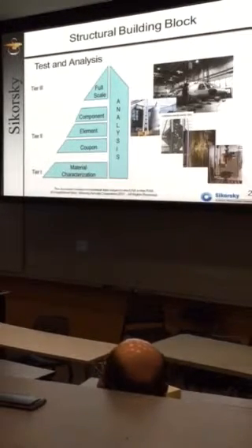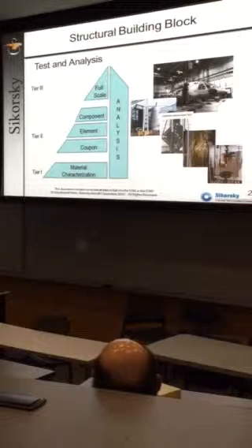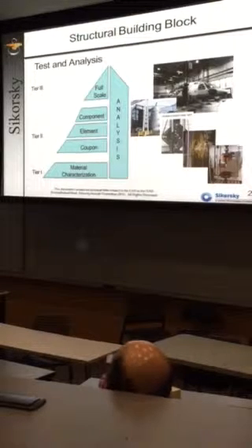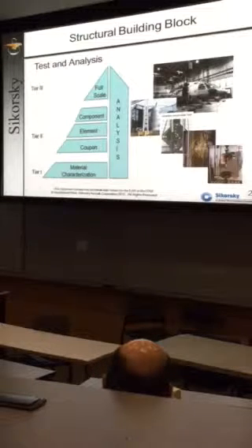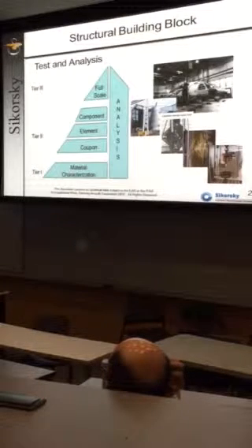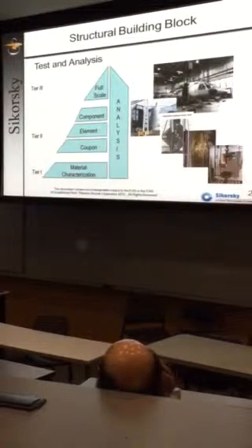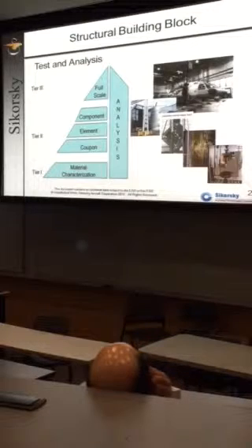That scales up then to components where we may take a full-scale blade or a full-scale transmission and run it through acceptance tests to prove that the element tests and our analytical theory on how we design that part are substantiated through testing. And then ultimately we get to a full-scale aircraft where we're loading it statically and then sometimes in fatigue. And then ultimately we have ground test vehicles that we fire up, load on the ground before we actually fly that aircraft, and then leading to a flight test.